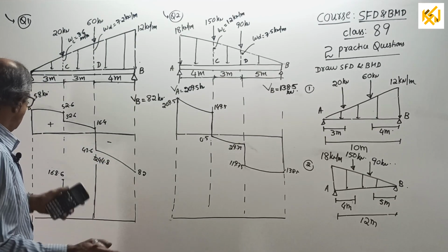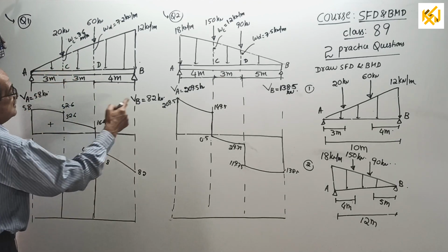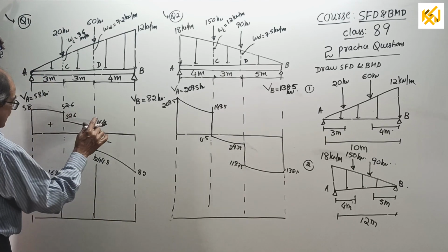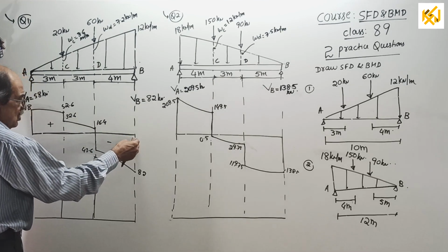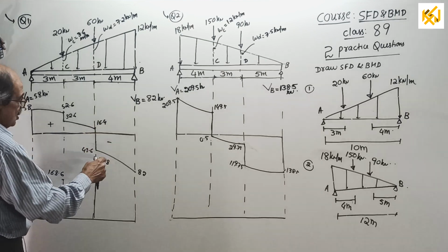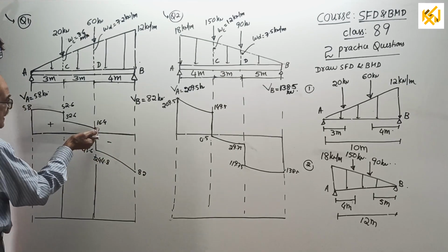244.8, you got there. Now important, here shear force is 58, here shear force 82, this side higher slope, this side lesser slope, and from here to here, slope should keep on decreasing. Here also, slope should decrease this way, and at this point, zero slope is not there, because why? Shear force is there. This side and that side, different slope will be there. Lesser slope this side.